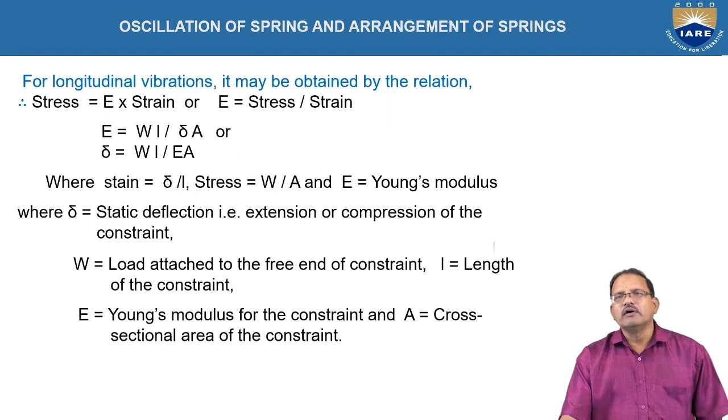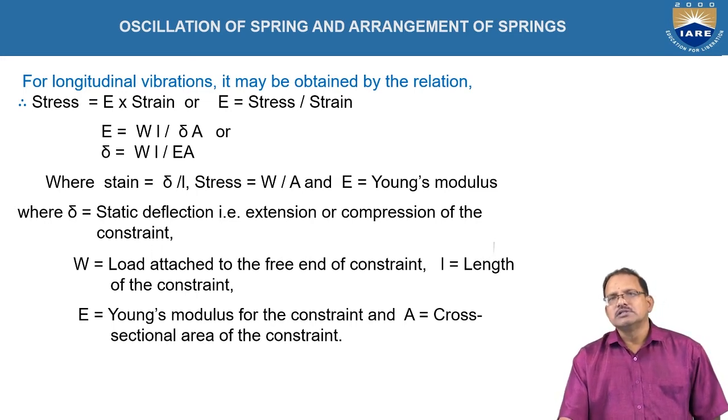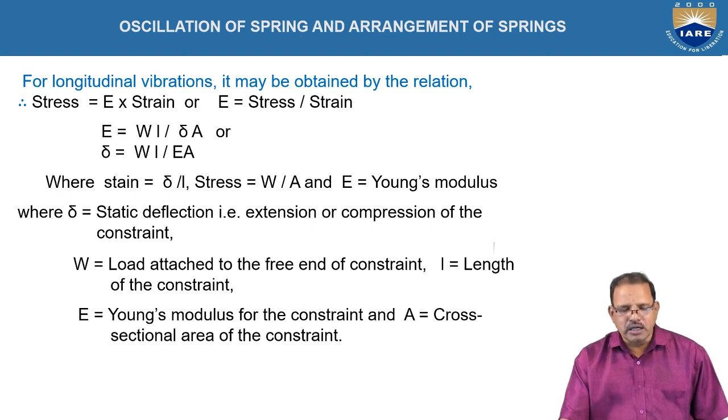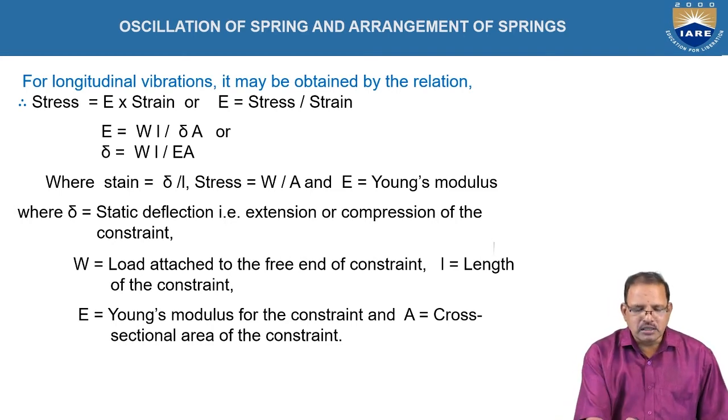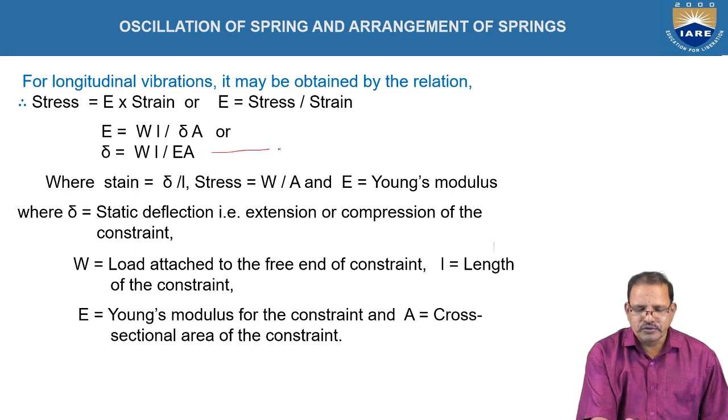For longitudinal vibrations, using the fundamentals of strength of materials, stress by strain is equal to Young's modulus. We get Young's modulus E equal to stress by strain, which is also equal to W·l divided by δ·A, or δ is equal to W·l divided by E·A, which is shown in equation number 6.